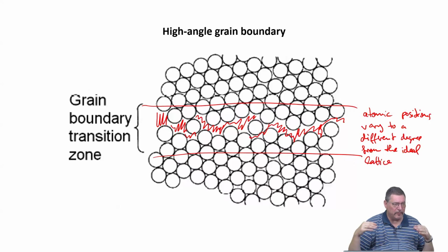They have observed how a dislocation is driven by external stress into a grain boundary by doing snapshot TEM analysis and observing the strain field of a single dislocation. At that time, high resolution was not yet possible. What does a dislocation do? You're absolutely right. Grain boundaries are sinks for dislocations, so they move into the boundary.